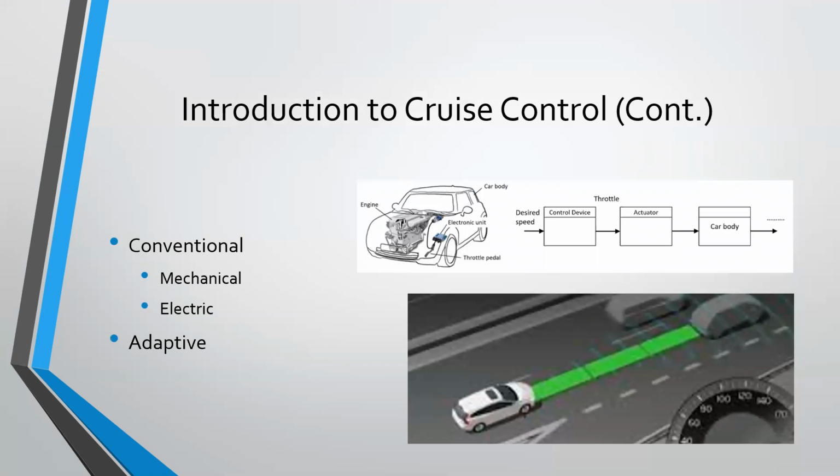Conventional cruise control systems' primary function is to adjust the throttle input of the vehicle to maintain a preset speed. The vehicle's instantaneous speed is constantly changing due to multiple factors while driving. These factors can include dampening force from the headwind against the vehicle, change in the grades of incline and declines in the road, as well as changes in the direction of the vehicle.